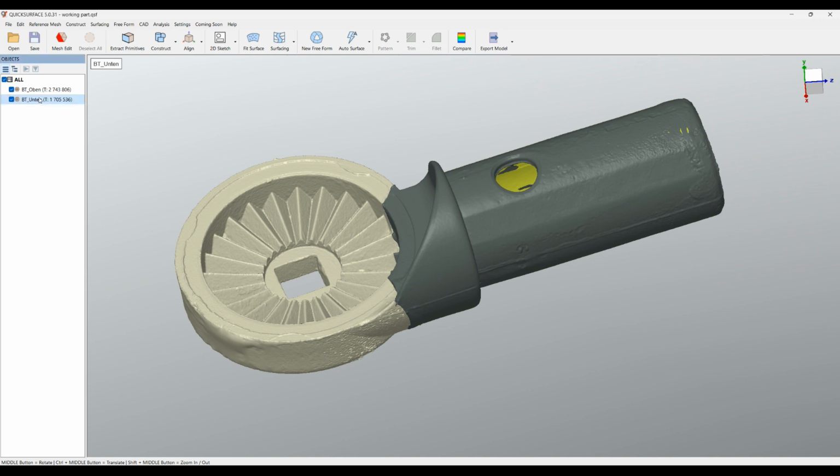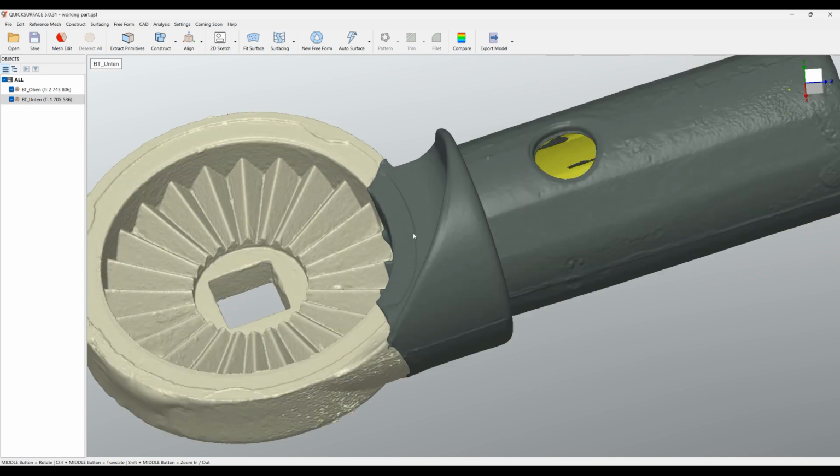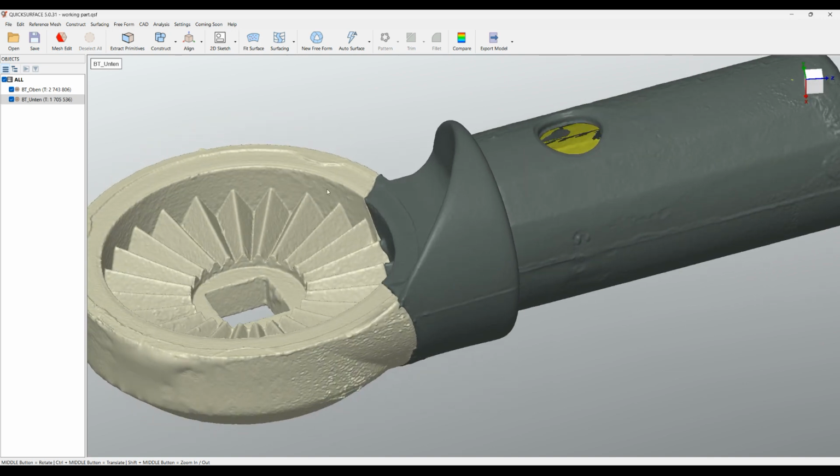Still, I have this mesh pre-selected. I can go to our last step, which is called fine align of the reference mesh. And here you specify the lookup distance between the two. The algorithm will take the active mesh and using the best fit will try to align as good as possible to our reference mesh. And you can see now it just prepares, and it didn't move a lot. The reason for this is because it tried to use a lot of the points in these meshes.